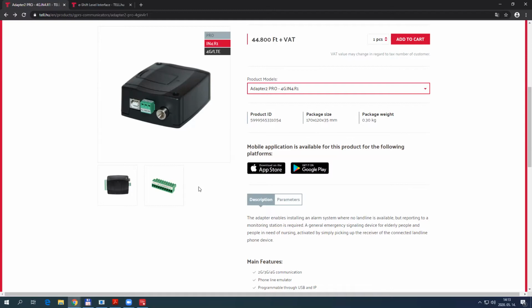The device reports the state of its 4 configurable normally open and normally closed contact inputs to central monitoring station and to mobile devices at the same time. Contact ID codes can be freely configured for each input event and service event with partition and zone number.